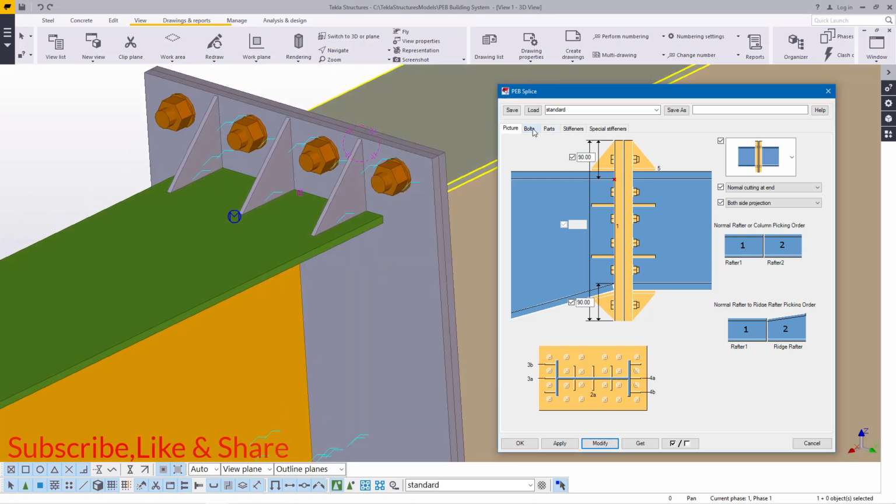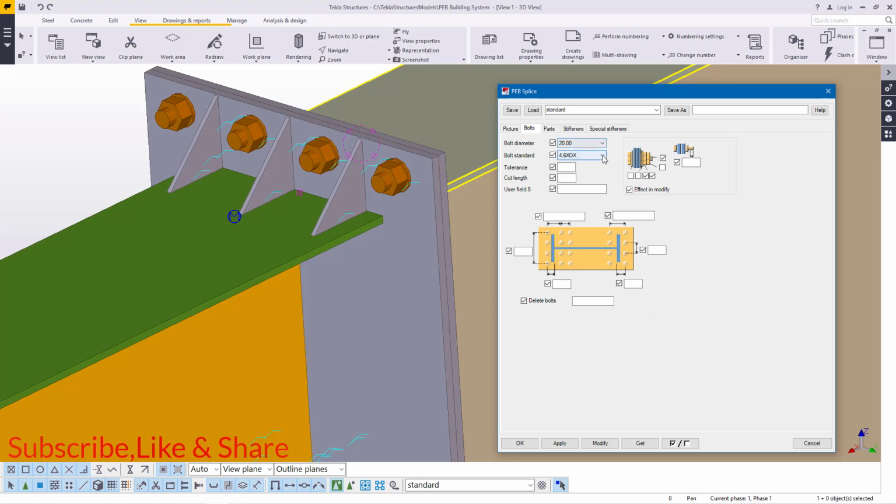And I'll go to the bolts and I'll use M20 and the bolt grade of 8.8, and in here I'll use 2 by 250, and here I'll just feed 0, and in here I'll feed 35, and here also I'll feed 35. Taking into account these are my preferred parameters, if you intend to use the same, you can apply the same.